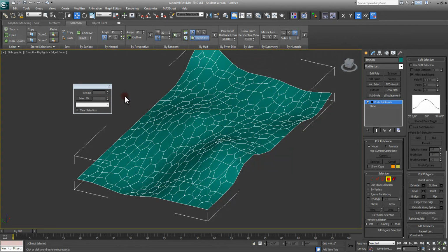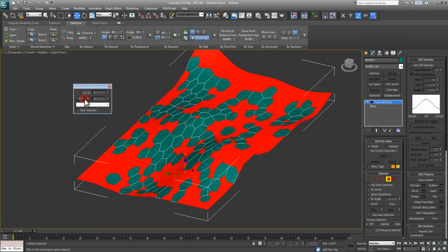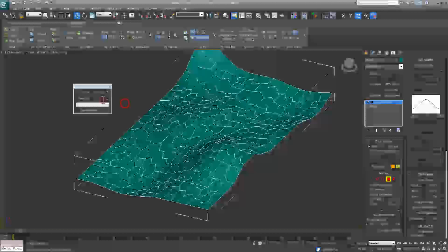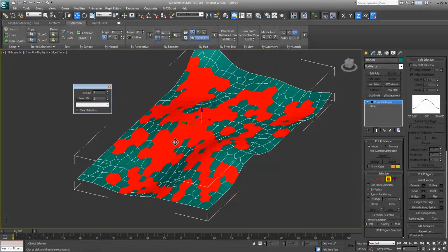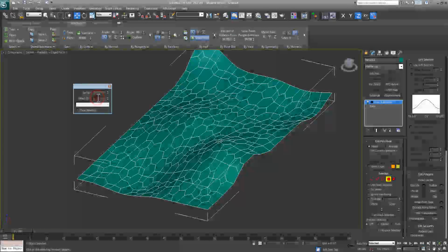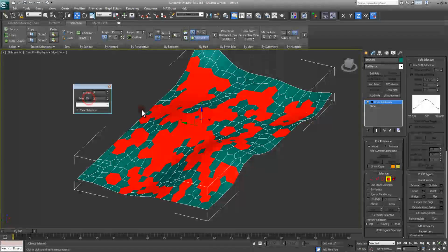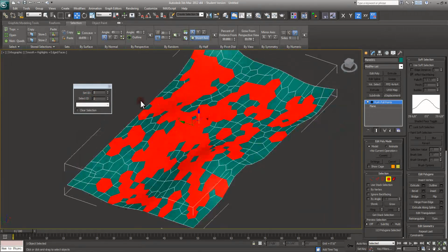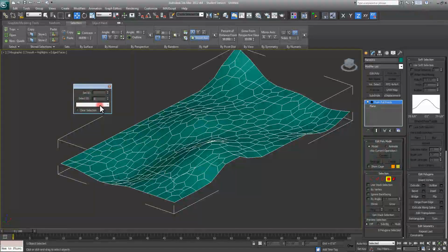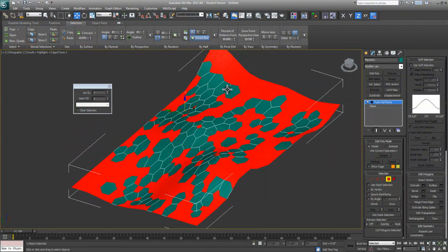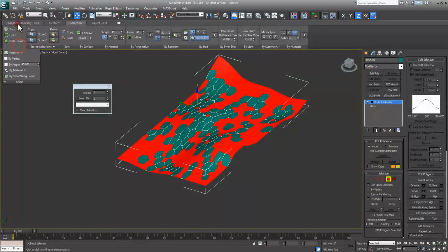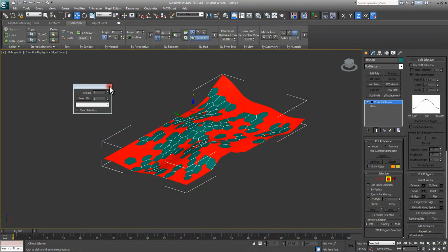And then what I'm going to do is click off of it, so then I can do ID 1, select. So that's everything on 1. And then ID 2, select. And that's everything on 2. So I actually had to click off of it. So if I do 1, select, I have to click off of it and then hit 2, select. So that's everything on ID 2 that I changed, and this is everything on ID 1. Again, there are some other more advanced, complicated things that you can do within here, but those are the basics of the selection tab within the Graphite Modeling tools.